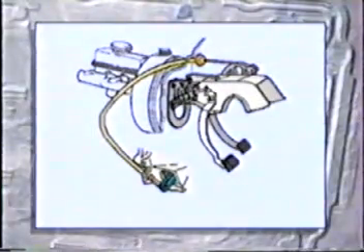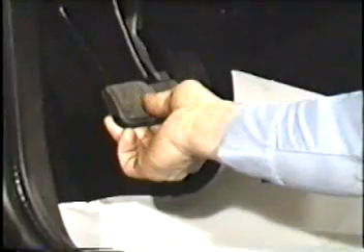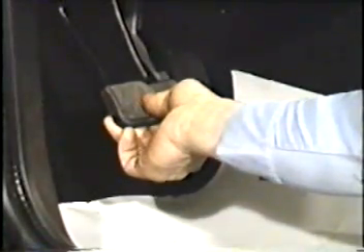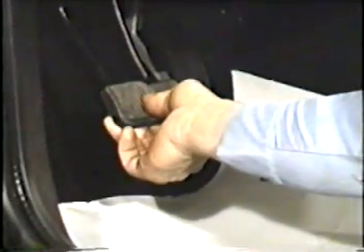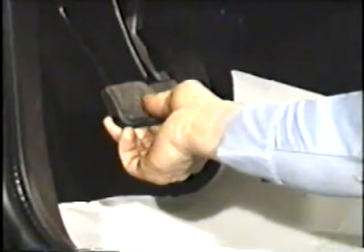When installing a new clutch cable, carefully follow the routing instructions in the manual. Once the cable is installed, the Mustang cable clutch control system is self-adjusting. Just lift the clutch pedal away from the floor for initial adjustment, and the mechanism will continually self-adjust from then on. While the cable clutch control system is still used on the Mustang, many current Ford vehicles use hydraulic clutch controls.